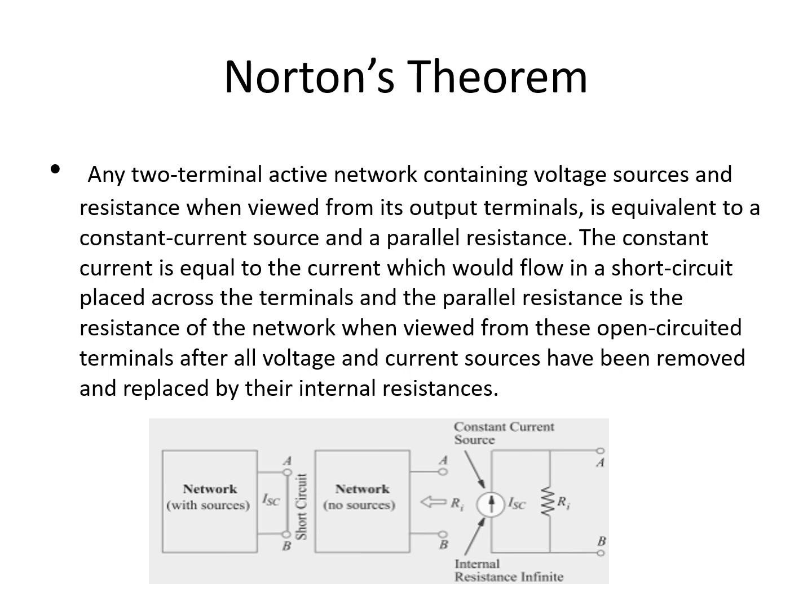Then we're going to get the Norton's resistance, removing the sources, leaving the resistances alone, we will get the internal resistance of the circuit. So for Thevenin's, that is a voltage source in series with an internal resistance, or the Thevenin's resistance. In Norton's case, it is a short circuit current. Before, it's an open circuit voltage.